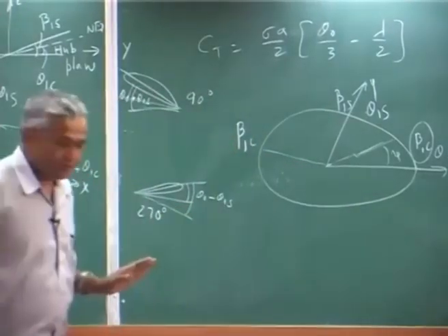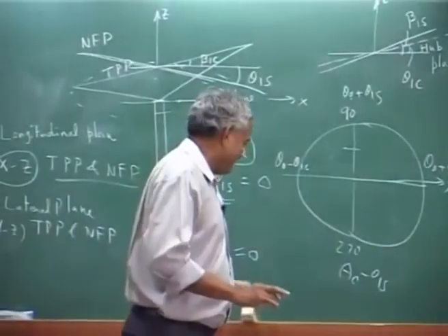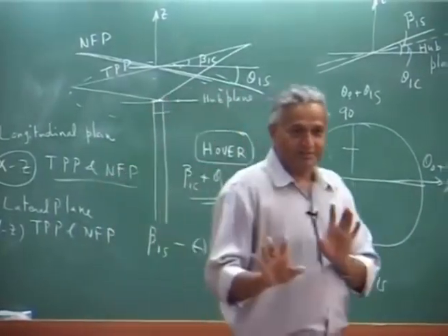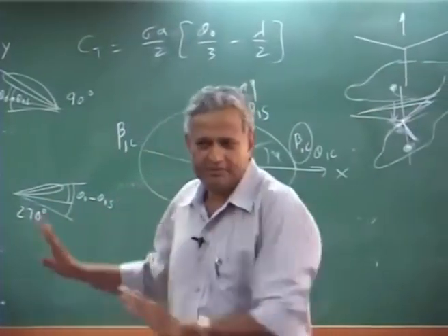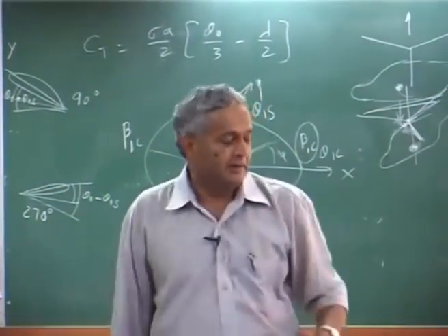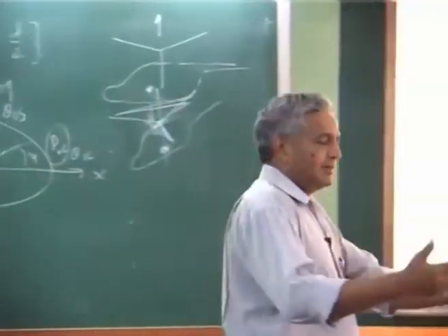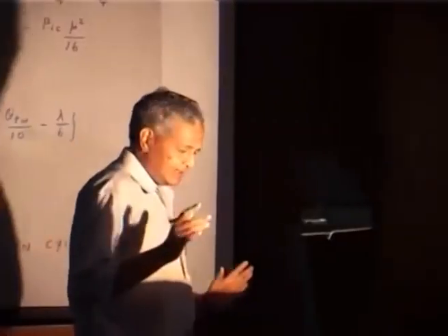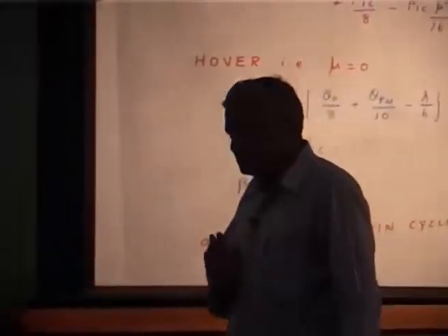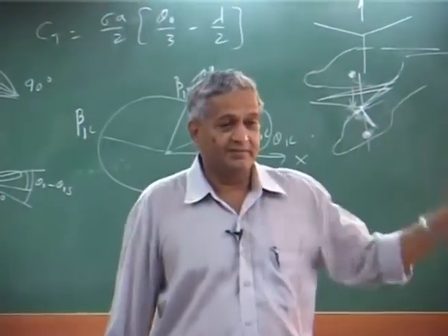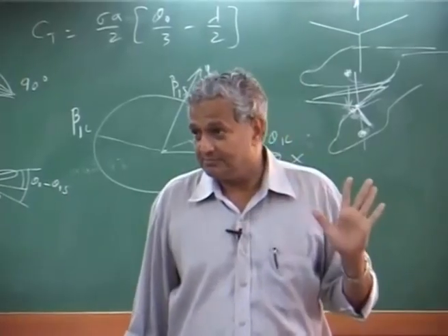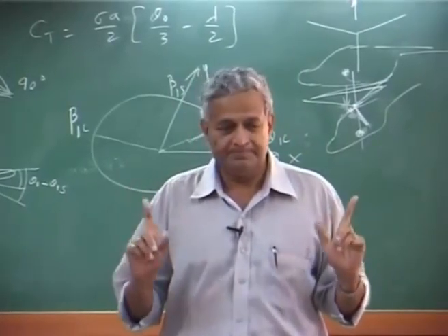Okay. Now, the major part of the flight, the relation between input to flap, is clear for a very simplified case. Now, if you complicate the problem, that is why usually industry will say the input phase shift is 90 degree, but 90 degree is valid only for centrally hinged with flap frequency 1 per rev, that is 1 omega.